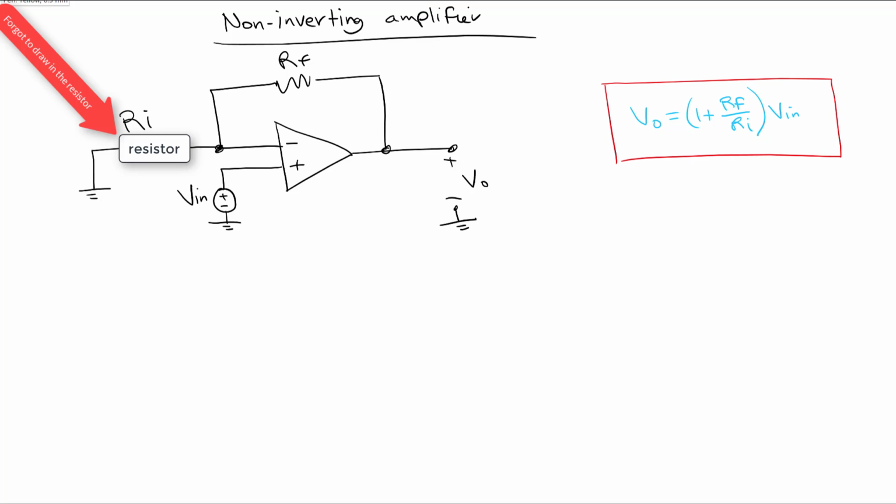Okay, so what do we see in this op-amp circuit? One of the things that we notice is that there's negative feedback. And again, for my little memory aid, I see the input signal going in to the positive input of the op-amp, and that makes me think, yeah, the gain is going to be positive. So it's just a memory aid for me.